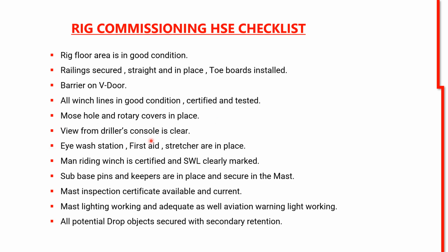View from the driller's console is clear. Eye wash station and first aid stretcher are in place. Man riding winch is certified and SWL clearly marked. Sub base pins and keepers are in place and secure in the mast. Mast inspection certificate available and current. Mast lighting working and adequate as well. Aviation working light, warning light is working.